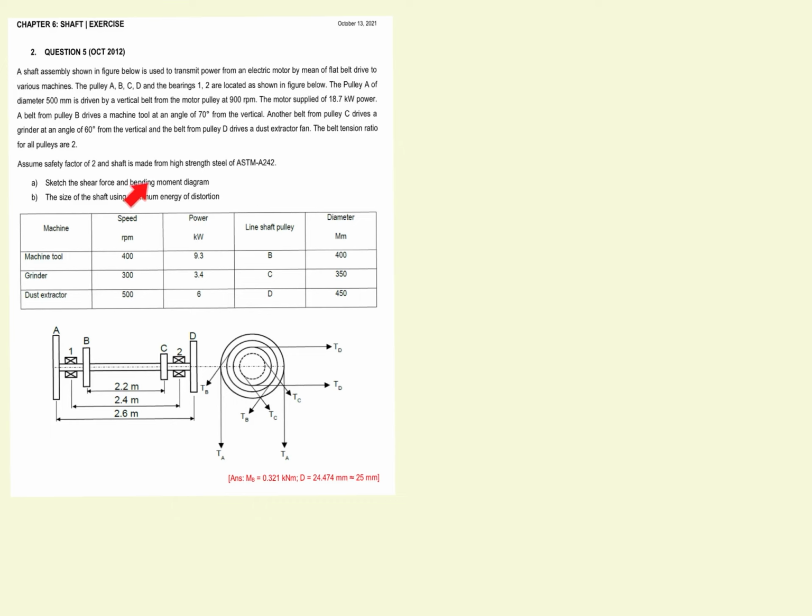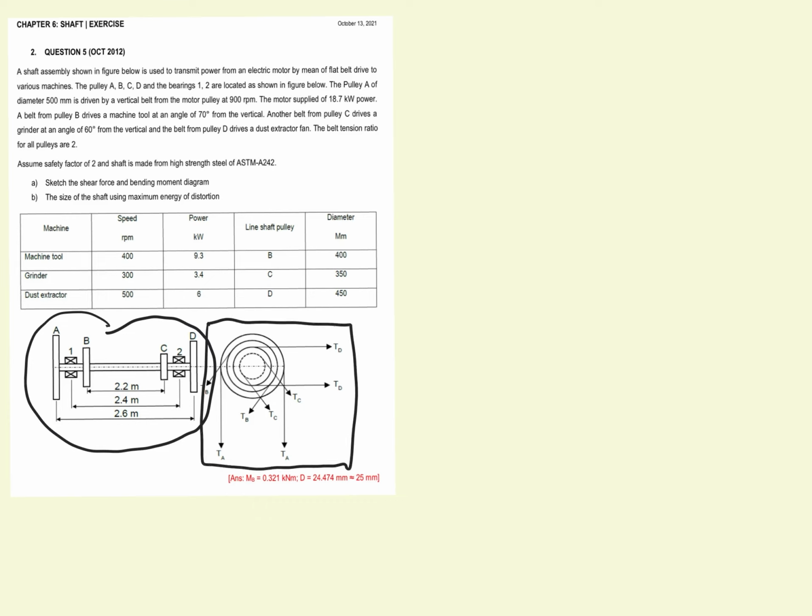Before we can sketch them, first we need to know the direction of the force and its value for this shaft assembly, because as you can see from this figure, the force is a combination of horizontal and vertical with the inclined angle above. So we need to resolve this force into x and y components.